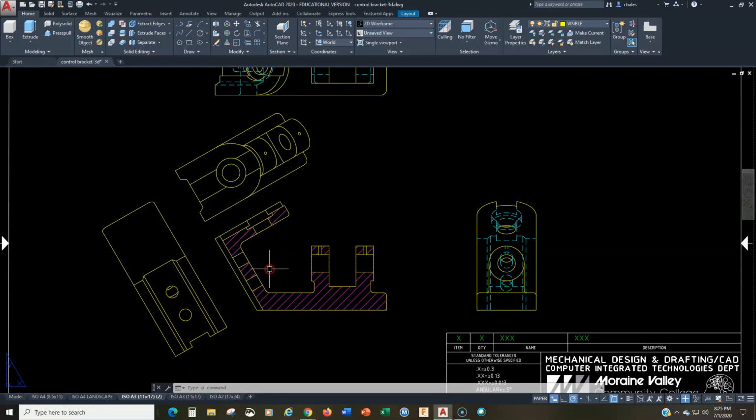Okay, so it's not pretty, but it definitely is all smart views. The only big problem here is that A, we can't really get partial views here, and B, these aren't aligned. These are manually aligned. This view right here and this view right here are aligned to the front view because we projected them. These are just manually aligned, just kind of loose views.